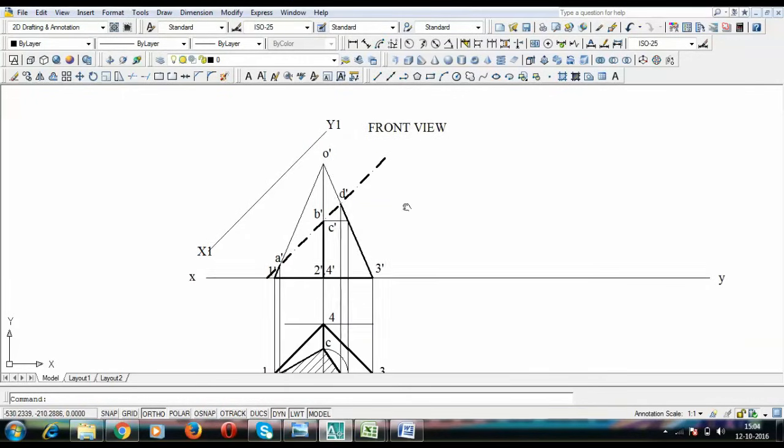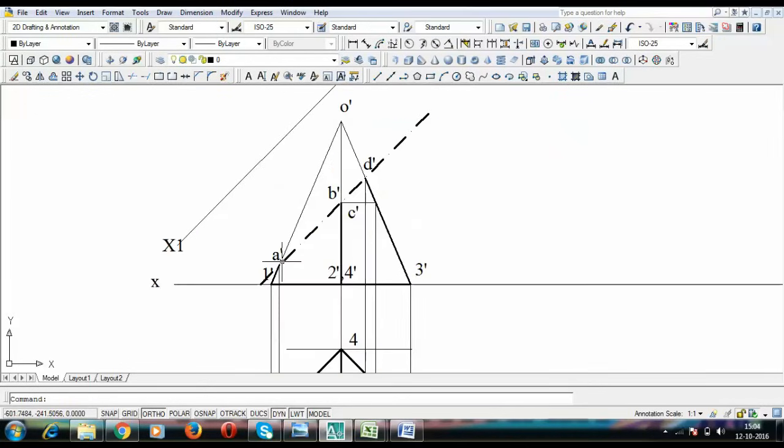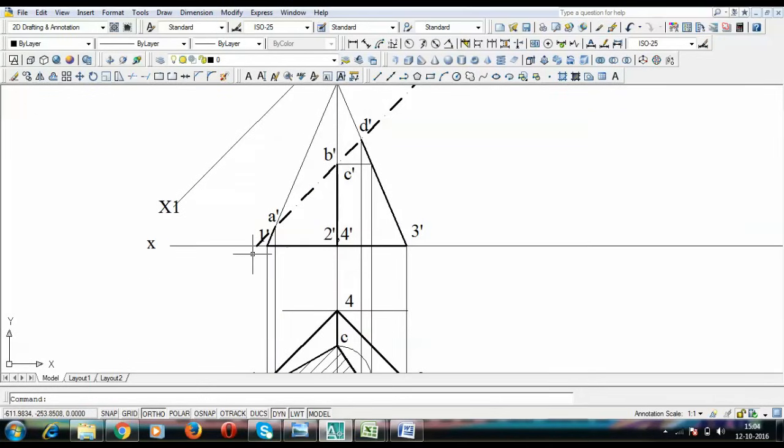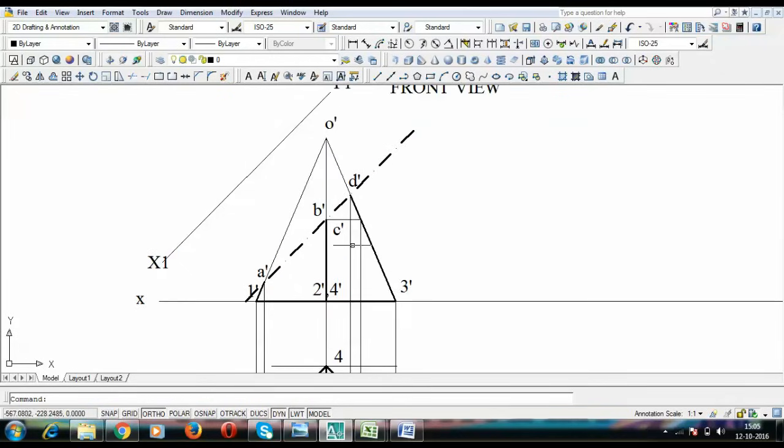All right, now we need to draw perpendicular lines from these intersecting points. So there are 1, 2 and 3. This point represents 2 different points. So there are going to be 3 lines from here, and they are going to be absolutely perpendicular to this one. What you can do is keep one scale of your drafter along this line so that the other scale becomes absolutely perpendicular. Tighten the screw, then keep on drawing lines and move parallel.